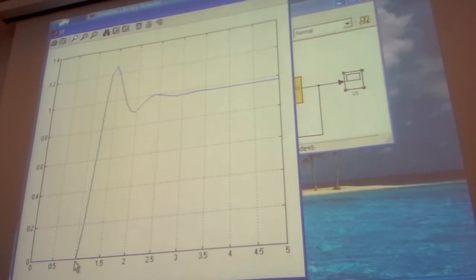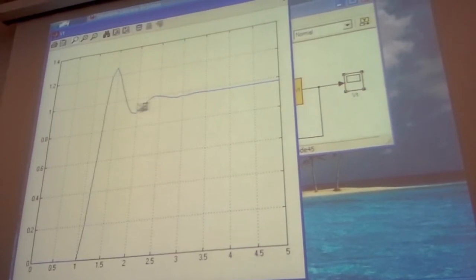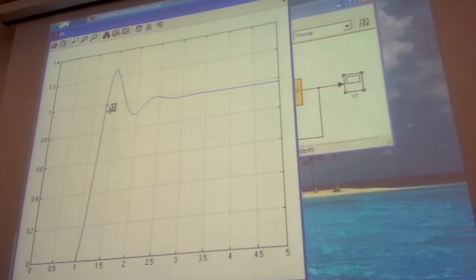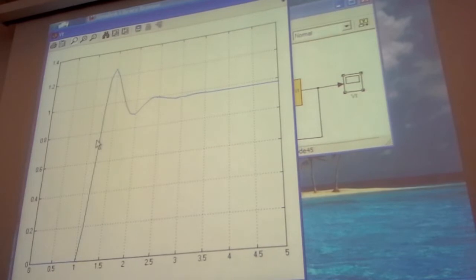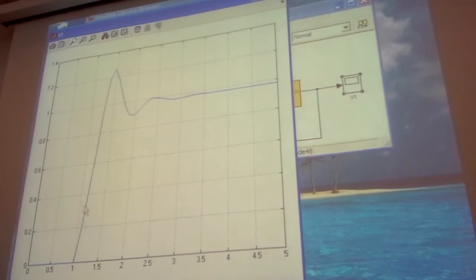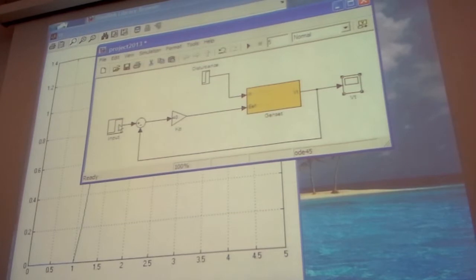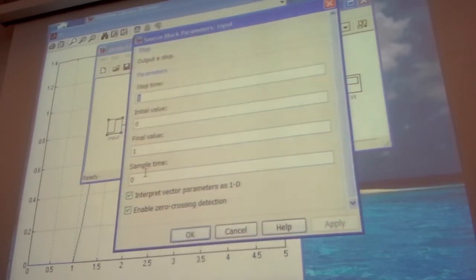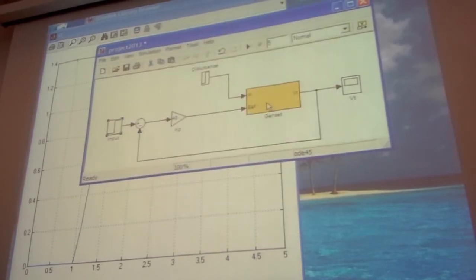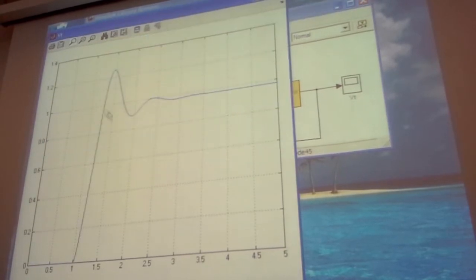Look at that. So the rising time is somewhere here, so about 0.5 seconds it goes up, right? Now, look at here, this one has fewer samples, here, here, here. The sampling is a problem, so I'm going to change the sampling time to 0.01. One change, and then the rest of it will follow that. Go to here. So we have a nice response there.